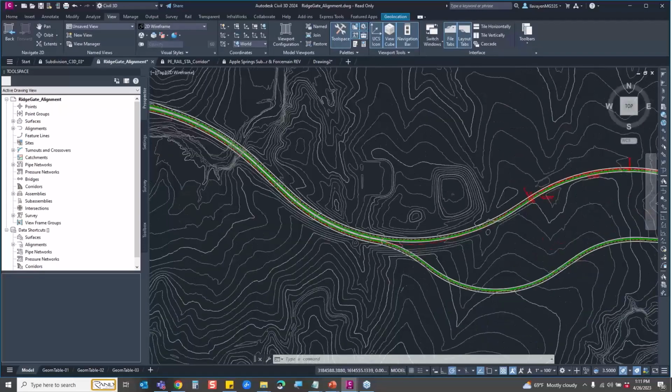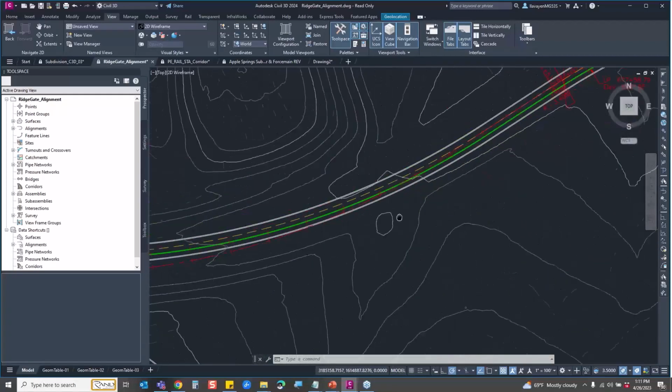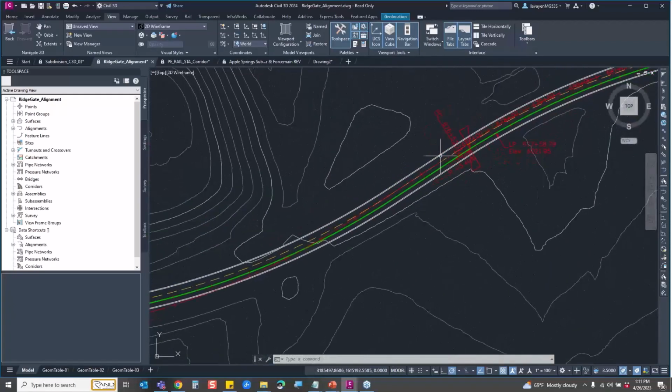What I want to talk about here is the alignment itself. See how the alignment has labels and all of a sudden they stop here? Well, that's because I've engaged this little button down here now. With that update, we get a new icon here at the bottom. And what I have here is the ability of either choosing to redraw every time I zoom and I pan, or redraw upon a regen for me here. So I can tell it go out here and regenerate or redraw the labels in this grouping for the grid that I'm looking at right now.